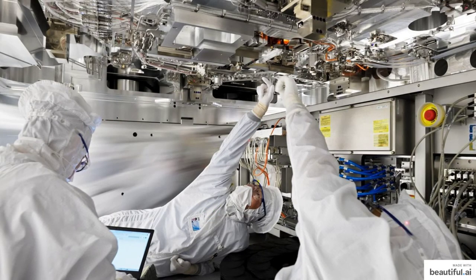Okay, so this whole process takes place in a zero-dust environment to reduce the rate of dust-related defects. Operators wear these bunny suits to make sure there are no more than 10 particles between 100 and 200 nanometers in size that are allowed inside 1 cubic meter of air within the clean room. To put that in perspective, a modern hospital has around 10,000 particles per cubic metre.